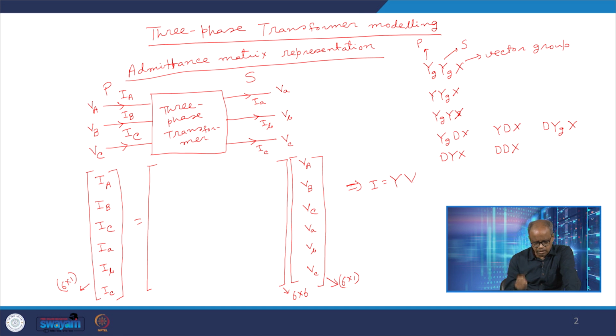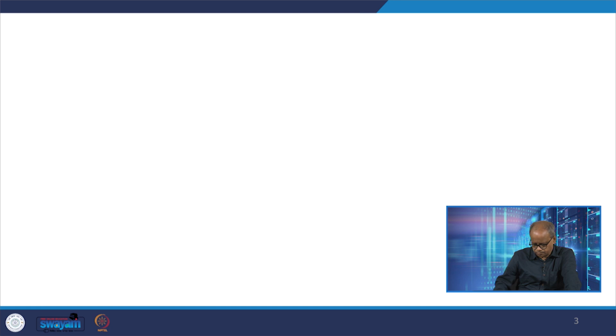It helps to incorporate this admittance matrix into the overall representation of any general three-phase network if we represent this Y bus matrix this way, instead of having I small a, I small b and I small c.